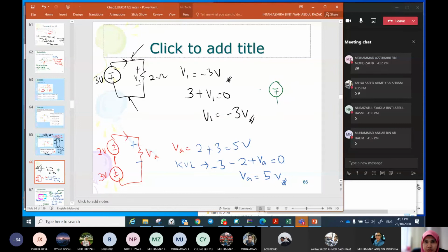We have, let's say, here is 2 volts, and then negative, positive. Also, we have 3 volt here. How about the voltage drop here? Current flows like this. Negative 5. Yeah, good. Why? Because when current flows here, the voltage drop will be positive and then negative. But the arrangement of the voltage source, we know that the voltage source here is minus 5.